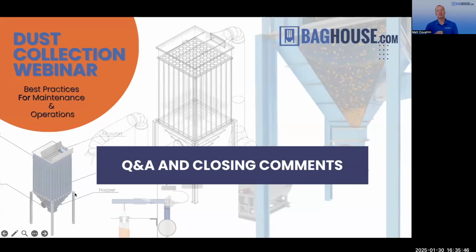You can also go into the dirty air side, and sometimes you can see where the dust has collected onto one particular cartridge. Say if there's a really big leak, you can see that everything wants to go to that leak, so it'll be coated with that UV powder stuff, and you can pick it up pretty easy.